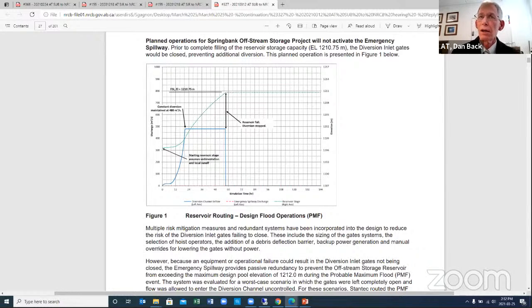I believe a 10,000 year recurrence interval event was used as the design event. I can't speak directly to where that motion occurred. There are source zones that those are developed from, and it would be a number of kilometers away from the site where that particular large motion would have been assumed to occur.